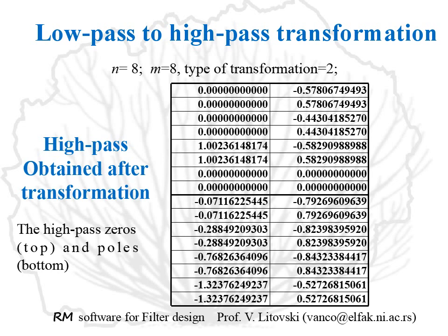Here is the example. Here is a low-pass, and here is the transformed solution obtained from the very same original which was discussed earlier. As you can see, the number of transmission zeros is increased by 2, so that the numerator and the denominator are of the same order, with 2 zeros in the origin.